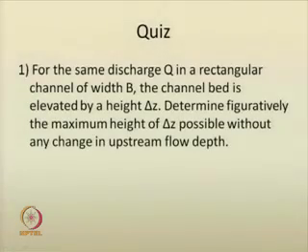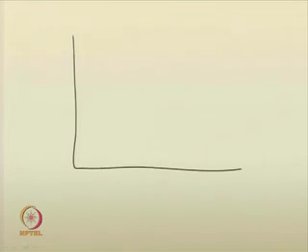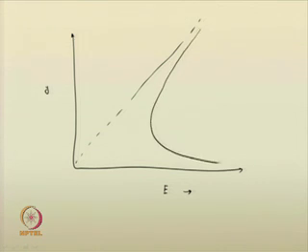So, the solution for the first question of today is, you can just draw a specific energy versus depth curve, the 45-degree line where depth of flow and specific energy are the same. You are just drawing a specific energy versus depth curve like this. Okay.